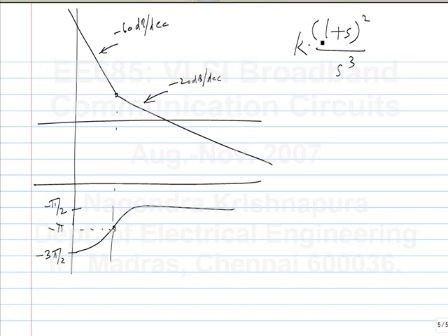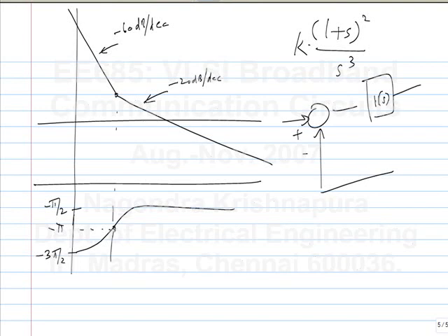Is this clear? Sometimes the intuition for negative feedback is given that you apply some signal, and some signal comes back and then gets added either in phase or out of phase. But in all those descriptions, you implicitly assume a delay. Even in the semantics, when you say something comes back, you assume some kind of extra delay beyond what is here. So if this is minus pi and this is more than 1, the feeling is that it is adding in phase and it's more than magnitude, so it will become unstable. No, it doesn't. So let's say this magnitude is 4.